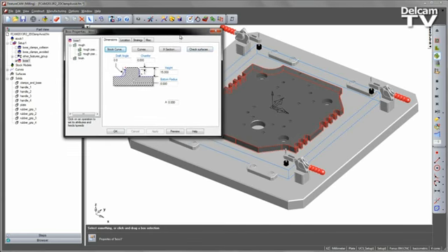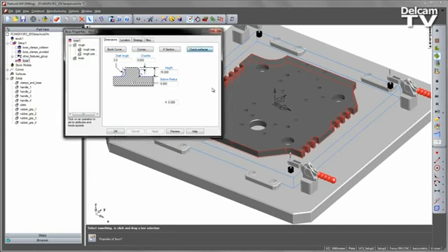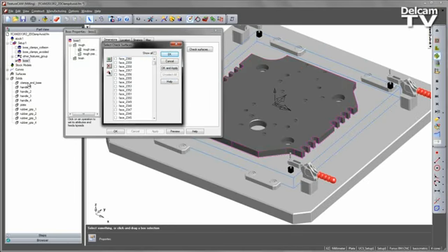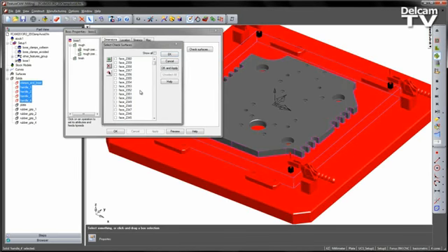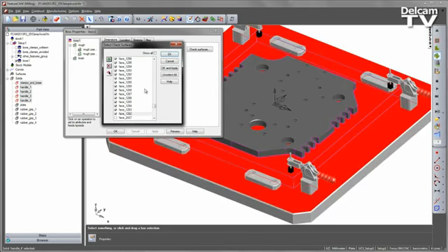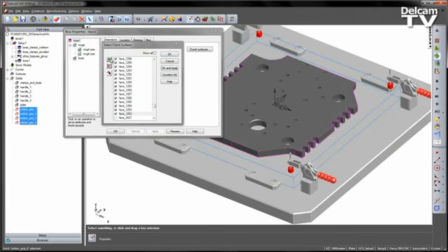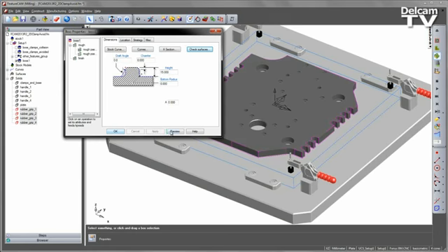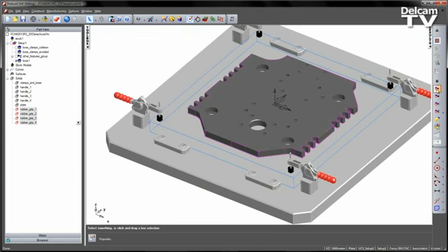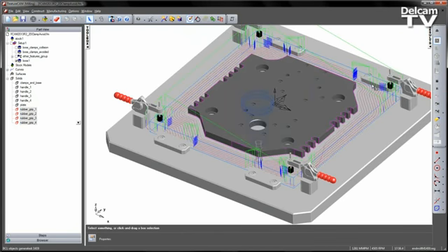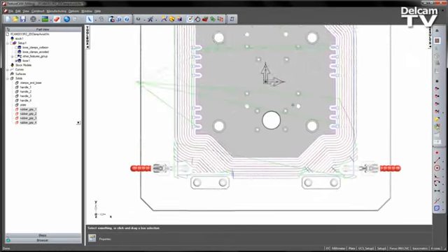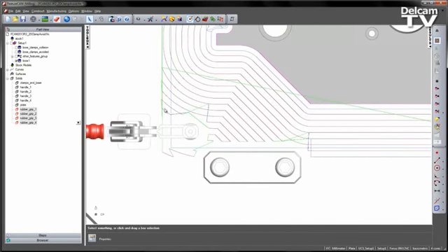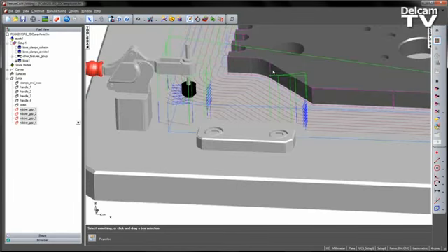I now want to bring in the surfaces of those clamps. So let's go in and select, and I can do this directly from my part view tree. So I'm going to select those and add those faces in, and also select the rubber grips and add those in as well. I can accept those. If I now do a preview of the toolpath, and we view from the top, we can now see that those clamps are being avoided. So the toolpath has been trimmed out.